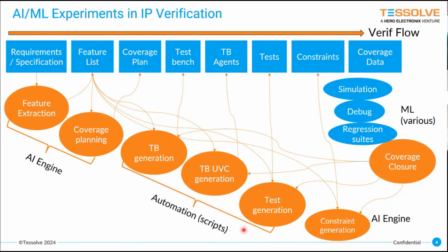What we use the Python for, it generates quite a lot of static parts of the test bench, the infrastructure, the static parts of the UVM, and then it will generate all the dynamic parts, the constraints, the sequence generation, the sequence items that are going to be generated, etc. That Python uses a config file, by the way. We use a config file for that.